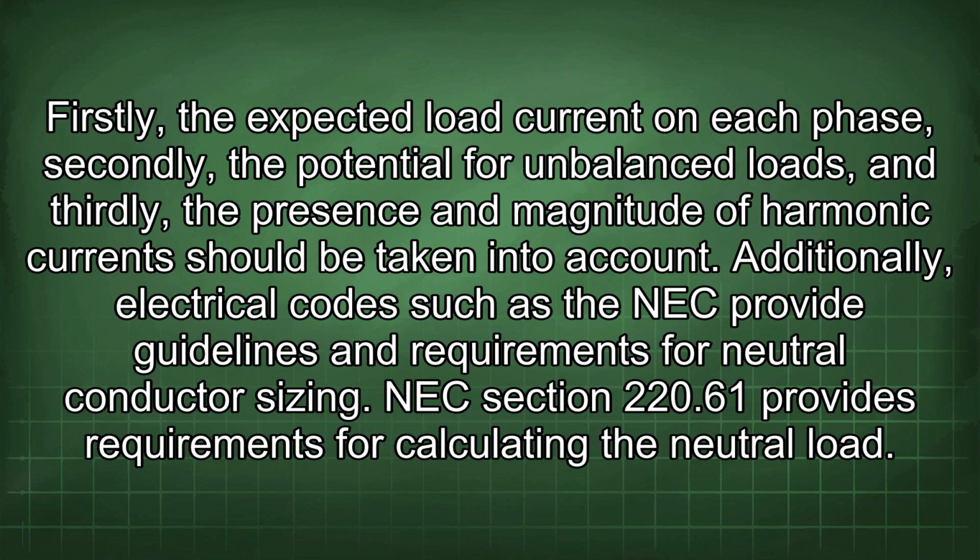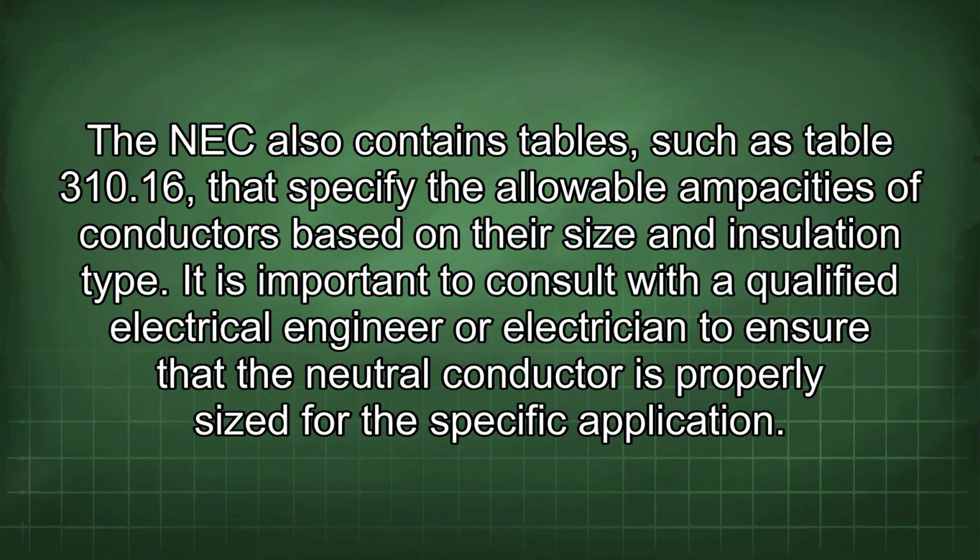NEC Section 220.61 provides requirements for calculating the neutral load. The NEC also contains tables, such as Table 310.16, that specify the allowable ampacities of conductors based on their size and insulation type. It is important to consult with a qualified electrical engineer or electrician to ensure that the neutral conductor is properly sized for the specific application.